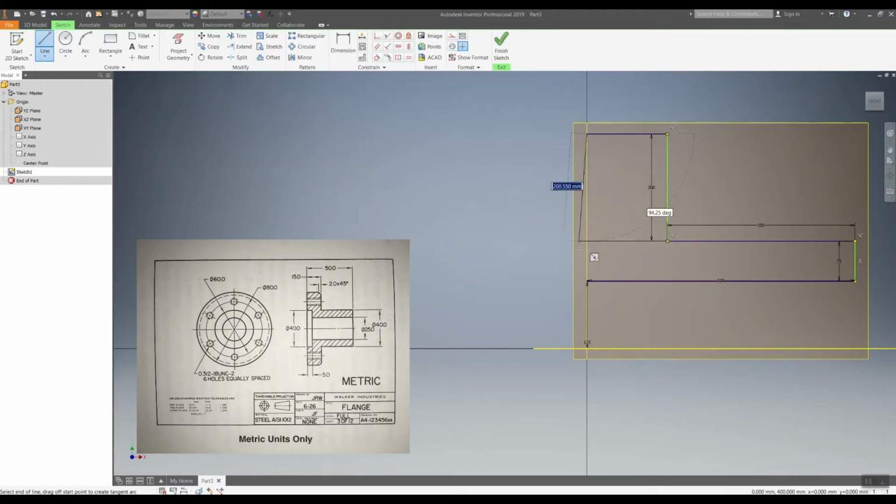Here it is, 150. And we are going to start coming down, but you're going to notice there's a little part of the flange that is cut out. You can see this little cutout starts right here at the 400. So that is 200 up. So if we go 200 down, which seems to line up with this line just like theirs, it says it's 50 over. So we go over 50, and then we go down here. Don't forget to get rid of this right here. Just delete that line. You could trim it too, and just connect your lines back up.